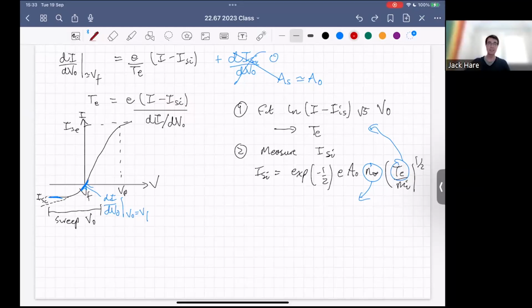How fast are these mechanisms? Oh, thank you, because my notes didn't update, and I'd actually made a new note on this that I did want to say. So let's talk about limitations. One limitation is you might draw I greater than the ion saturation current. You don't know where VF is to start with. So when you put your probe in and start adjusting the voltage, you might accidentally draw too much and melt the probe. We'll look at some other designs which are safe and don't ever do that. So this is a disadvantage of this design.